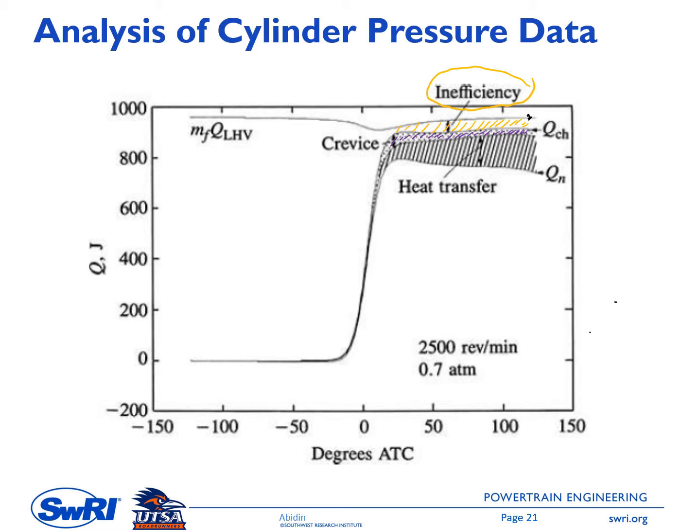And then we have a decent fraction of the energy loss because of the wall heat transfer. And then the lowest one here is showing the net heat release. This one is in terms of the mechanical work, so this is the P dV plus the delta U, the change of the mixture internal energy. So this example of result can be obtained from the previous formula.